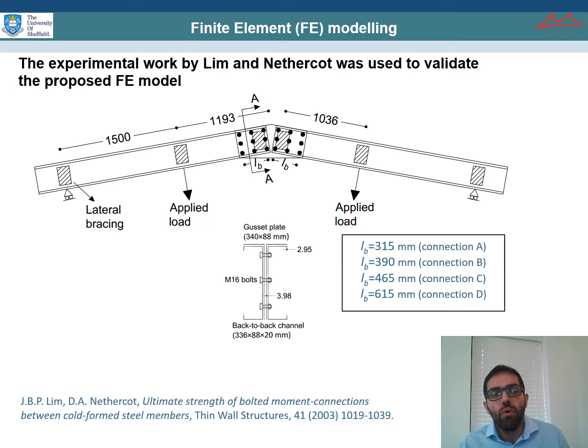The experimental work conducted by Lim and Nethercutt was used to validate our finite element models. Lim and Nethercutt conducted a 4-point bending test on the apex connection, and the beam element in this connection has back-to-back channel sections with the dimensions as you can see in the picture, and 9 M16 bolts were used to connect the back-to-back channels to the gusset plate.